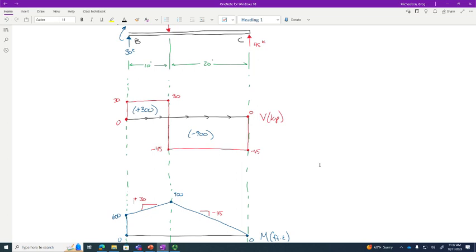Remember how the virtual analysis would go? We would kick off all the loads, and then we would replace all the loads with just a single unit force where we wanted to find the deflection in the assumed direction, right? And then we would analyze the structure again, sum up our energy, and that was our answer, right? We're going to do the same thing with beams. Same process, same method. There is one key difference, though, in the nature of the problem, okay?